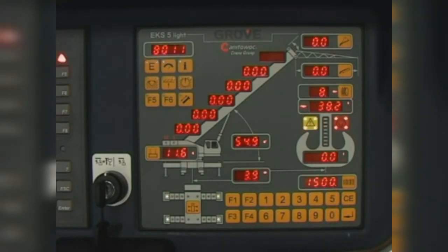The display will then configure automatically depending on the expired time since it was last used. If less than 48 hours, the last entered reeving and RCI operating codes are loaded as shown. If these still correspond to the crane's current operating configuration, you can press the enter buttons for reeving and RCI operating codes. This will remove the signal points after the entries to accept the reeving and RCI operating codes.